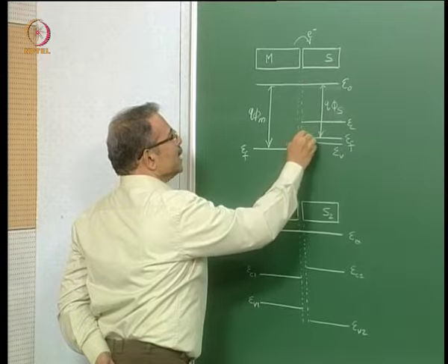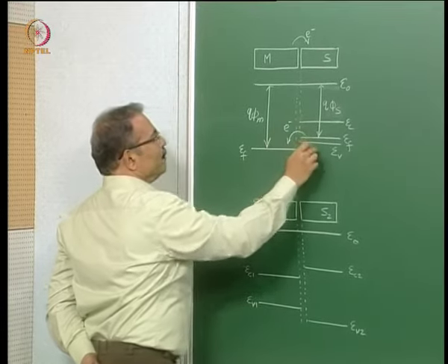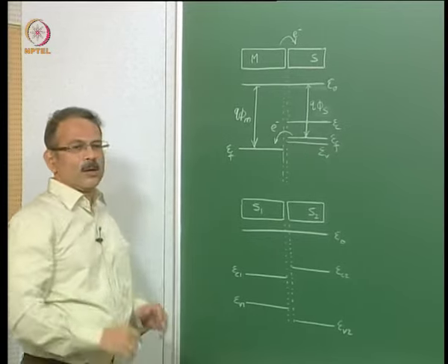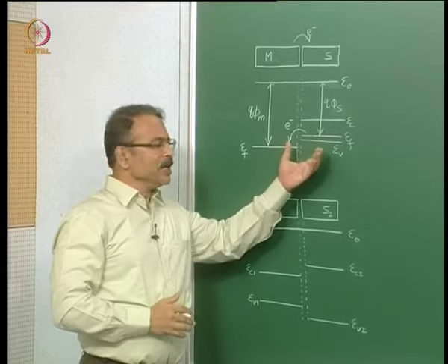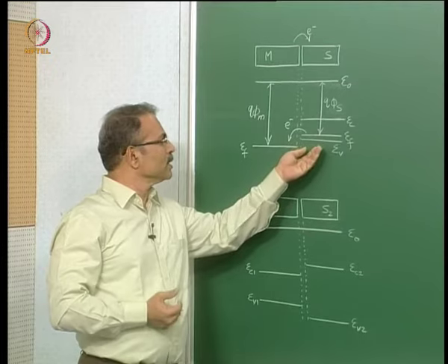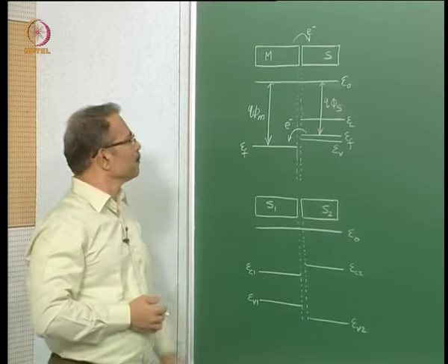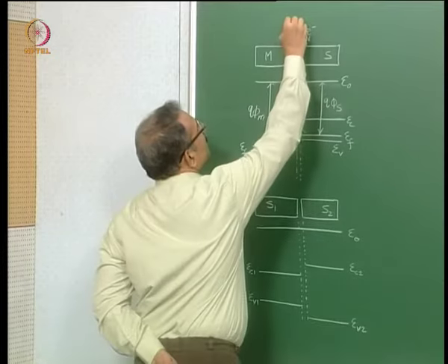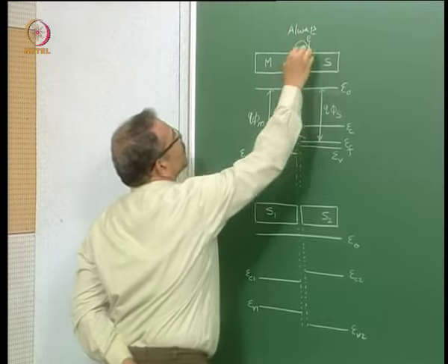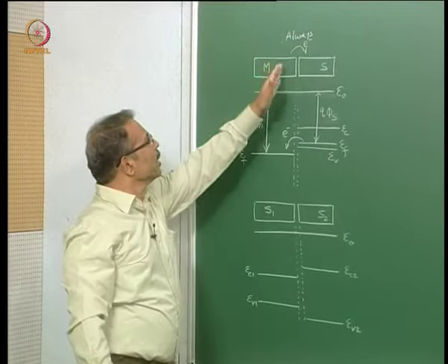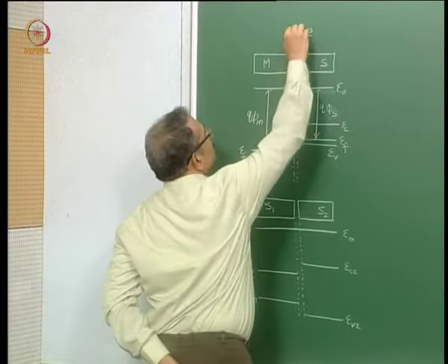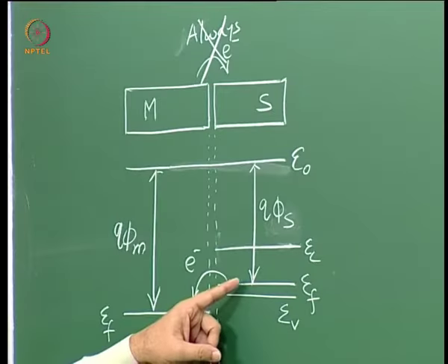So in this case electrons will be transferred from p type semiconductor to metal, even though the electron concentration here is small. This is because the guiding principle is the energy. Even though the electron concentration is small on the semiconductor side, the energy of electrons is higher because the Fermi level is higher. So if you think that electrons are always transferred from metal to semiconductor because metal always has higher concentration of electrons than semiconductor, then this understanding is not correct. You must go by the Fermi level locations.